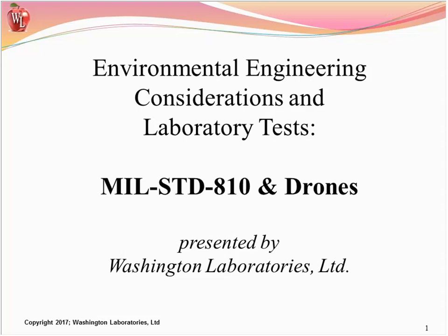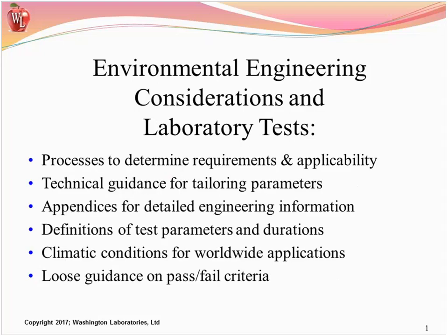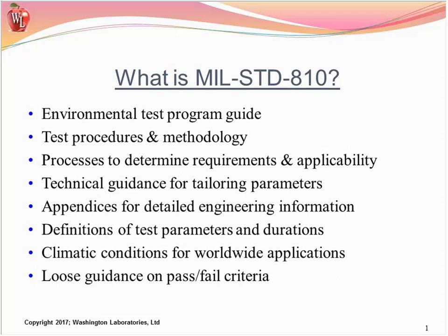So in the first one, MIL Standard 810 is one of a number of various environmental test plans that can be used for drones and a large amount of other things. 810 is primarily used for U.S. military. It's also used for a lot of COTS, commercial off-the-shelf equipment, used by the military. There are some other standards, DO 160 and IEC 668 are also similar. It covers a lot of the different test procedures and the methodology, calibration requirements, that sort of thing, basically all the technical details required for it.